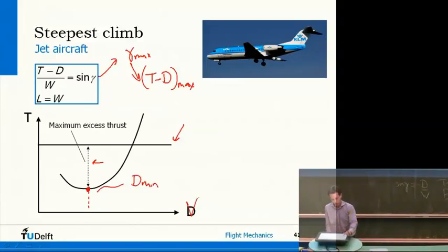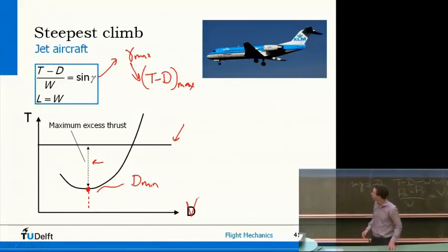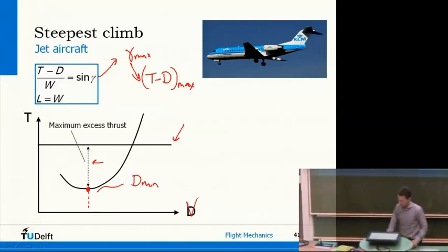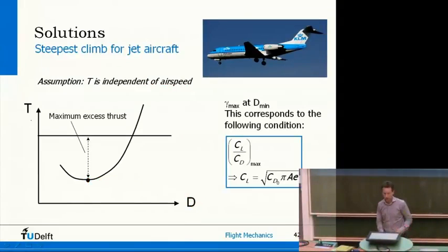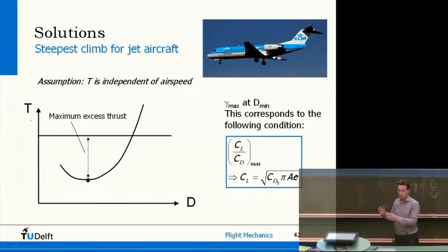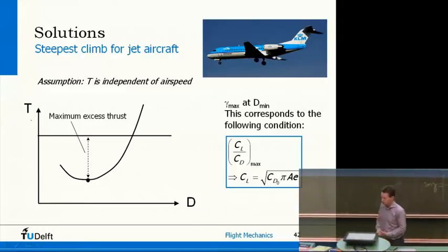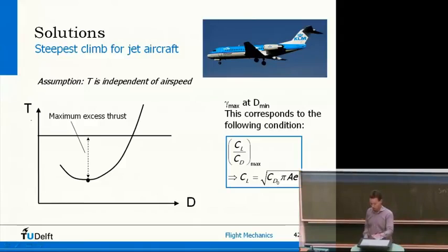So this is thrust or drag, and the x-axis is airspeed. So you can read straight away what's the airspeed, and again, as we already seen, that for minimum drag you should have maximum lift over drag ratio. Again, that same CL value, which is a matter of constants basically, and if you know that, you can calculate airspeed.